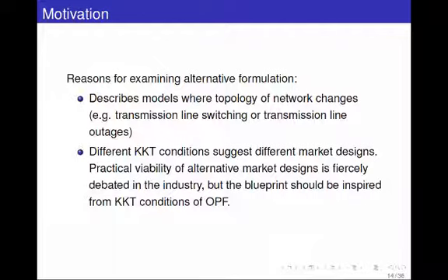So I can write the OPF model either using this or this. It's the same physical model. It describes the same engineering system, but it makes a huge difference in terms of designing a market behind it, because the KKT conditions we get here are used for designing markets and products for transmission, and depending on the KKT conditions, you create different, basically different products for different markets.